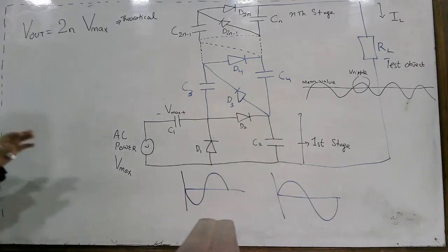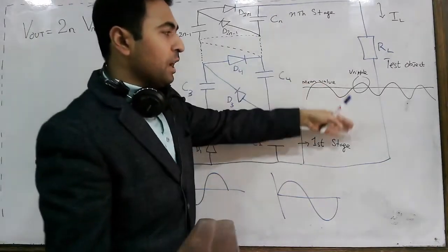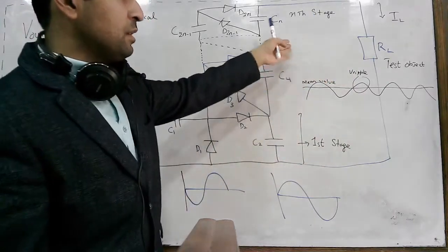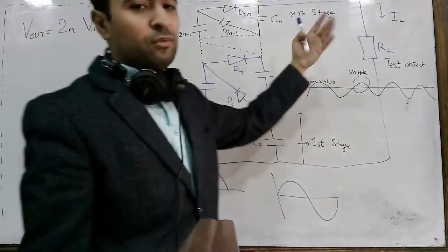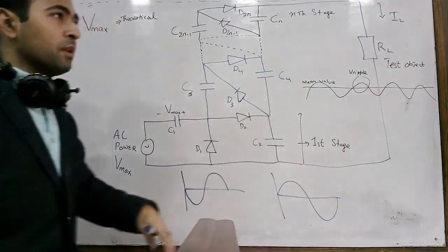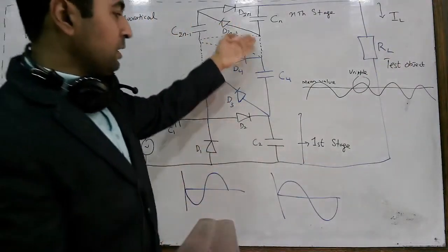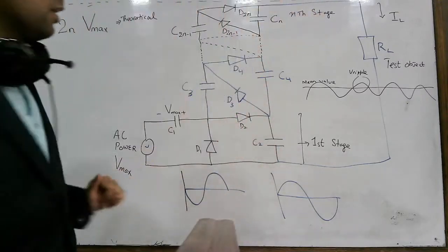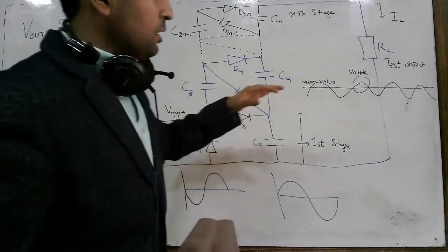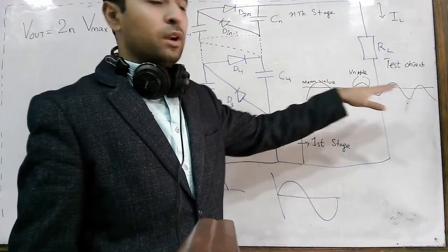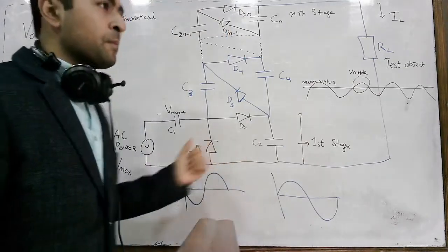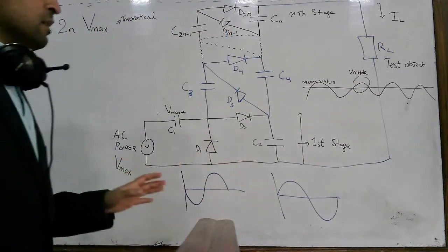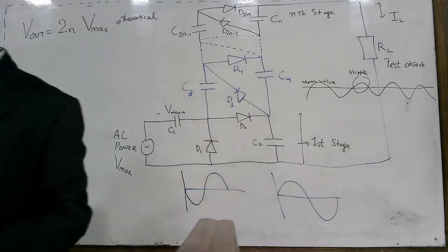Okay, so you got my point that here you will have the DC waveform and DC value. It means that obviously we don't have pure DC after the rectifier. Although we have the capacitors here, something is smoothed out. More to add, we always have the mean value and we have the voltage ripples. So what are those values? They are our major concerns. So let's discuss these things.